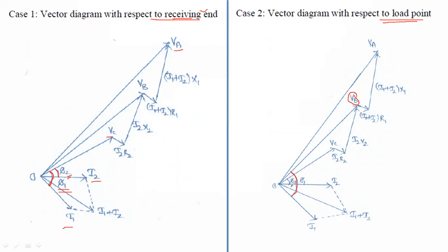In this section, we have discussed the radial distribution system, ring distribution system, and interconnected distribution system. If n number of distributors are connected, they go for the interconnected system. If the number of connected substations or generating stations is minimum, they go for the ring distribution system. And we have discussed the AC distribution network, that is how we can calculate the voltage drop, and the major difference between the voltage drop calculation of AC distribution and DC distribution. And we have seen one practical example of the AC distribution voltage calculation, taken for the radial distribution system.